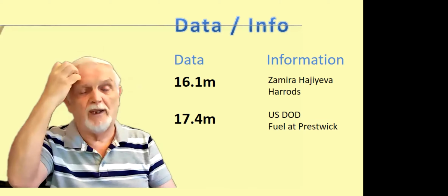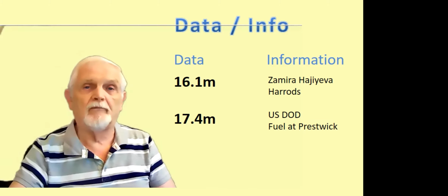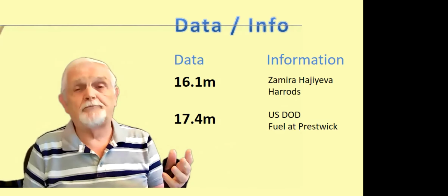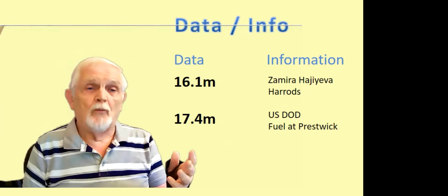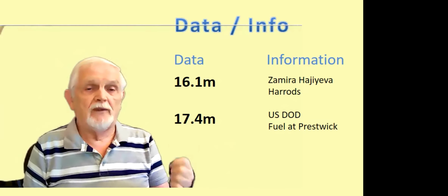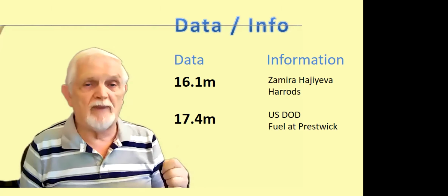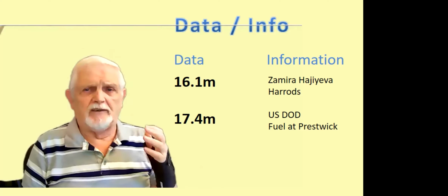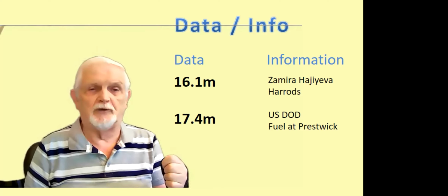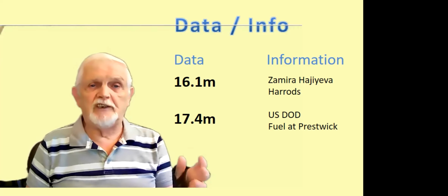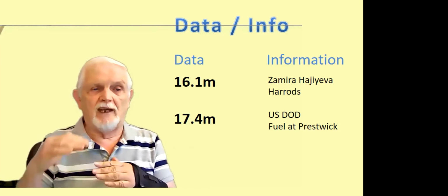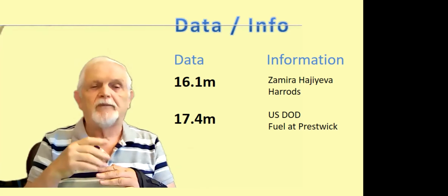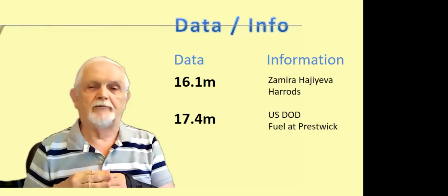You'll see, for example, in DCC, we have configuration variables, numbers that simply mean if you call up that number, it means go in reverse or go at half speed or a certain acceleration, a certain deceleration, and so on. And every DCC decoder must meet that basic spec for forward, reverse, fast, slow, lights, and so on.